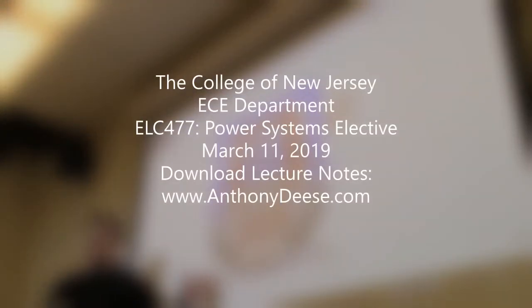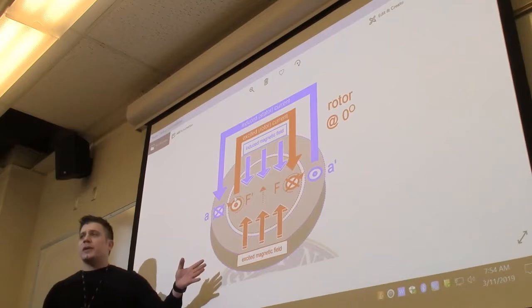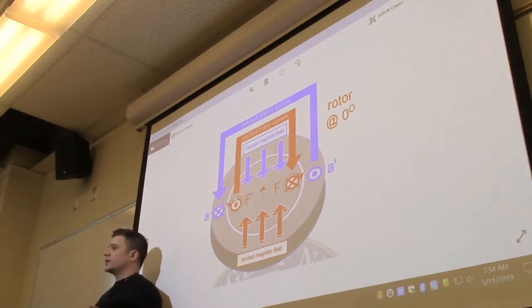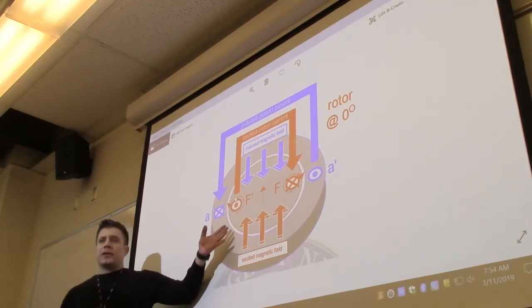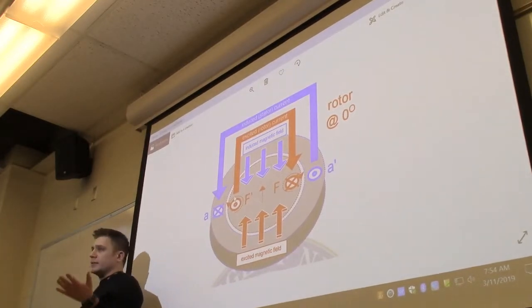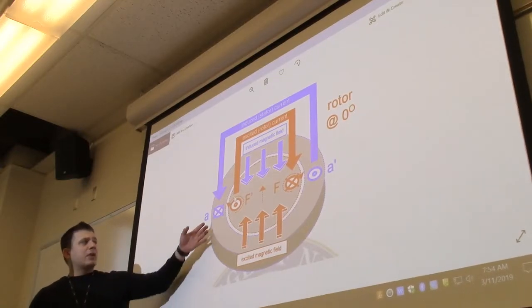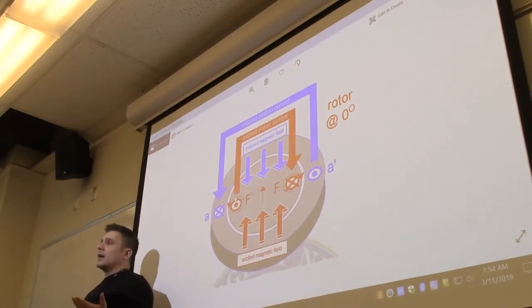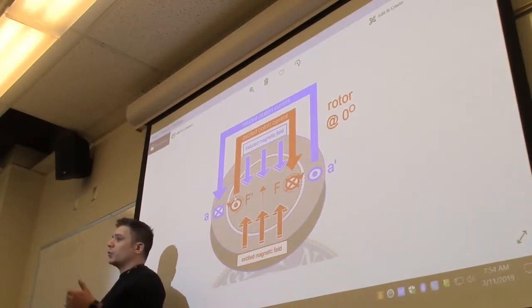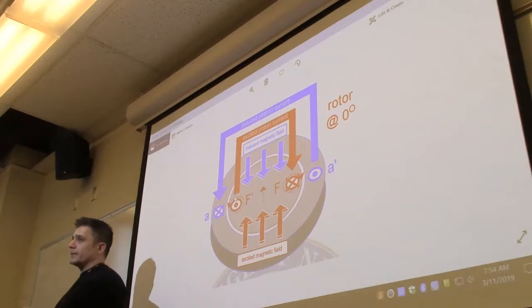Last time we had just barely dug into the surface. This is one of the figures that we looked at last time that represents the way a synchronous generator works. We have major pieces, stator, rotor. The piece on the outside doesn't turn, the piece on the inside does. We have the stator windings, which are embedded in the static part of the generator, and those are the ones on which we have the currents flowing that are actually going out to the equipment in the field.